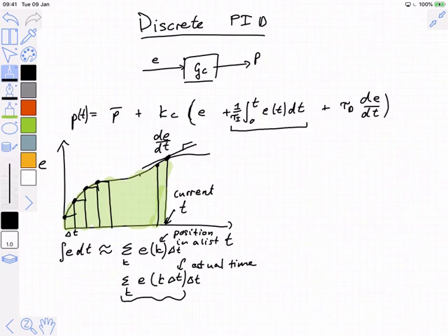And so for this reason, while mathematically you have done Riemann sums going both ways and done derivative estimates using backward differences, forward differences, and central differences in your mathematical courses, we will only use the backward difference approximation when we are building causal devices, because that's the only thing that can calculate at the current time without having to wait for future information to become available.